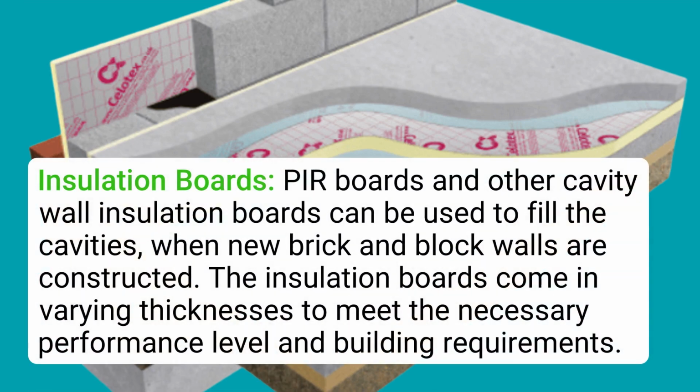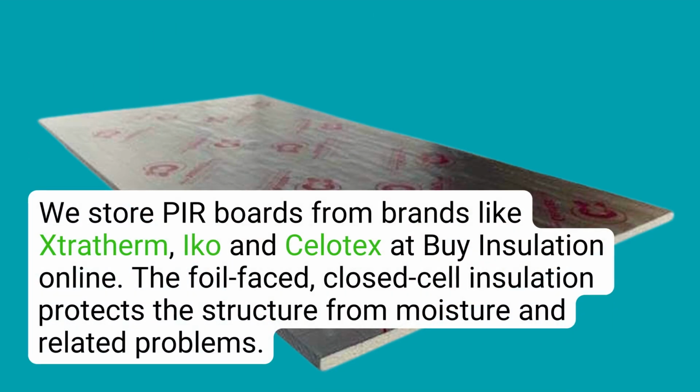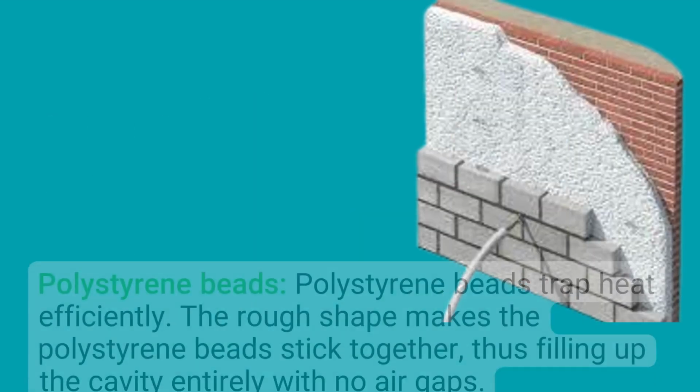Insulation boards. PIR boards and other cavity wall insulation boards can be used to fill the cavities when new brick and block walls are constructed. The insulation boards come in varying thicknesses to meet the necessary performance level and building requirements. We store PIR boards from brands like Xtratherm, Eco, and Celotex at Buy Insulation Online. The foil-faced, closed-cell insulation protects the structure from moisture and related problems.